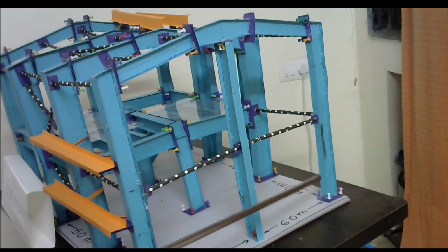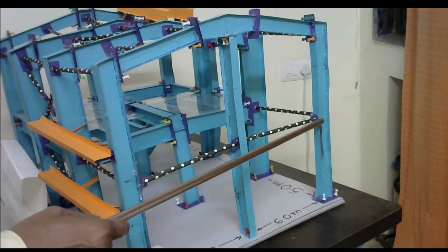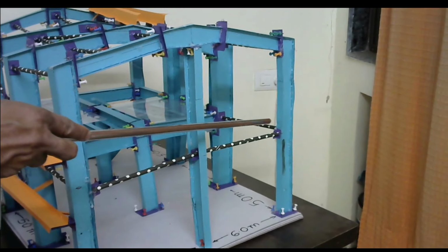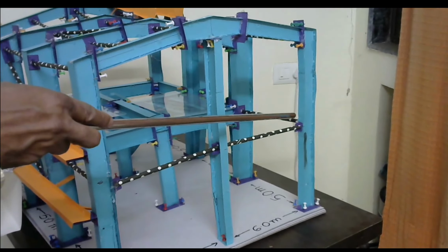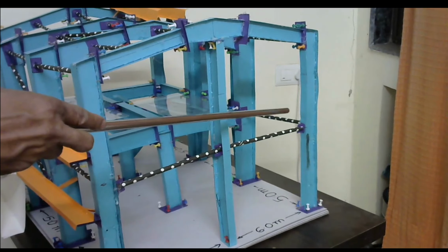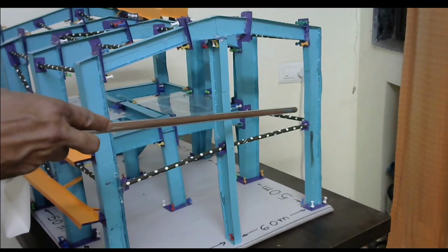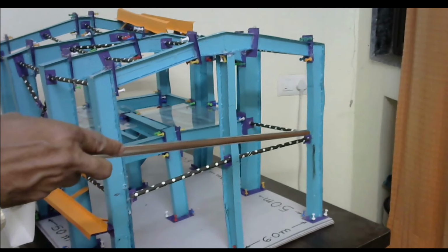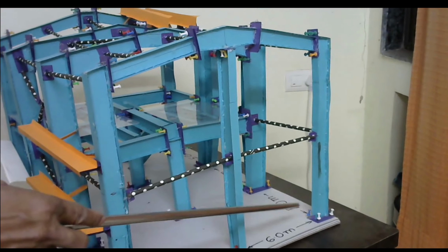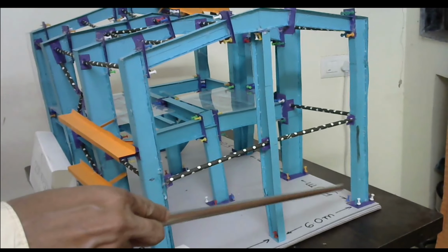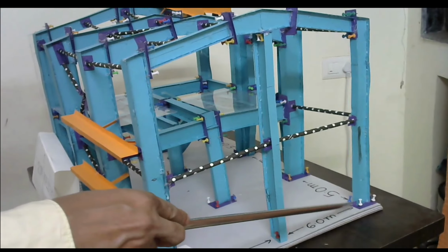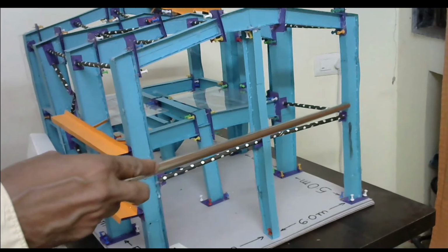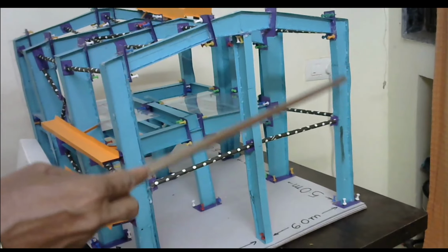So there is an end plate for this section. So this will provide lateral restraint, torsional restraint to the warping, twisting of the column. The flanges are not restrained, but we can always take as one. So LX is 2 into 3, bottom fixed, top released, 2 into 3, 6 meter. For the top part also it remains the same thing.